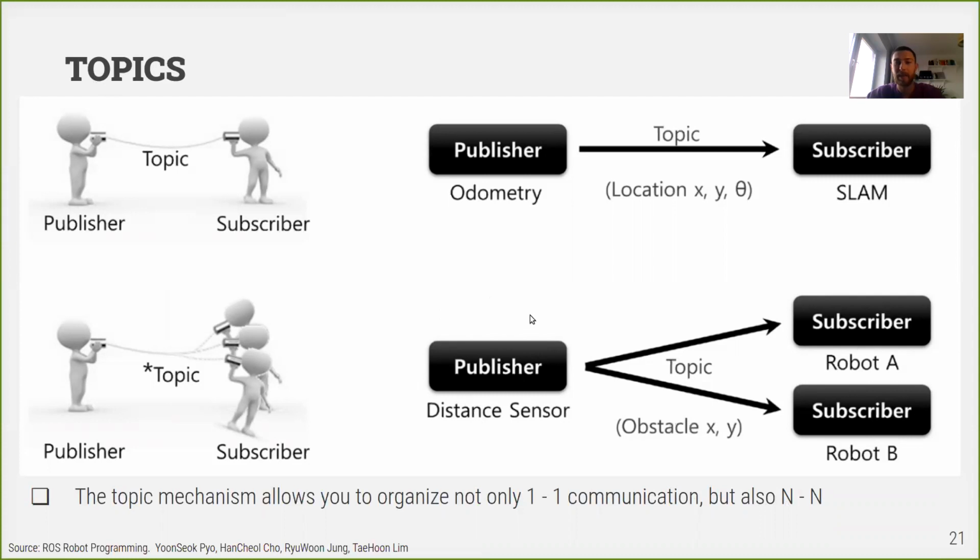So this is streaming type communication. So data is streamed continuously. This is something we have to keep in mind when we're designing our system, that in topics, data is streamed continuously. And for example, if you have some huge pieces of data which do not change, it is not really convenient to use this type of communication. Imagine a static map. For example, we have a map server and we want to publish a map. But if we know that this map is static, it doesn't change, it doesn't make sense to publish it continuously, because it is a heavy operation which takes a lot of resources to publish this map.